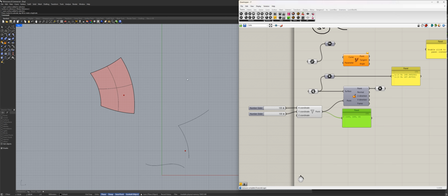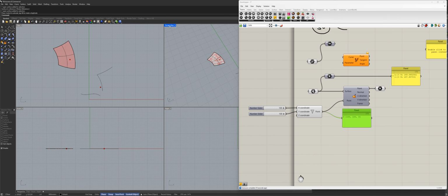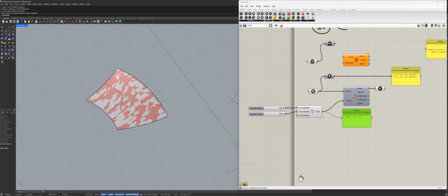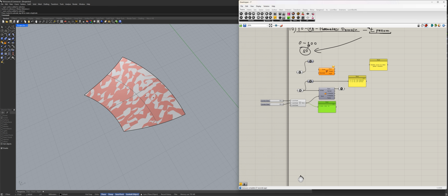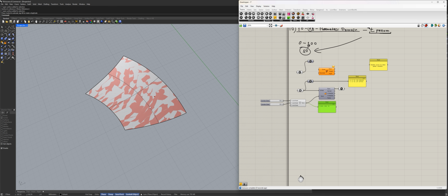We agreed on that, and this is what it is. And in fact, if I go into, let's say, perspective mode here, let me hide this. Sometimes I just want to hide something, right? So that Grasshopper temporarily doesn't visualize anything, because I have a Z buffer effect right now, because of the tessellation. So I'll go to the top right corner, and instead of this icon, I click on this one. It hides everything Grasshopper can visualize. This one will be outlines and points, and this one will be geometry. So I'll click on this one temporarily.